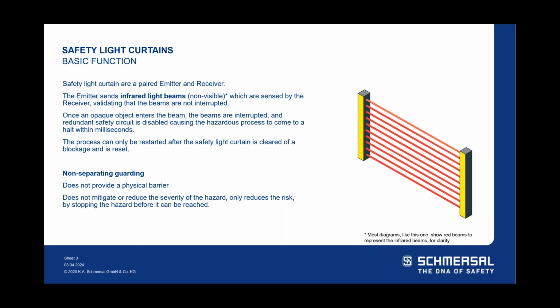All right, basic functions of a light curtain. Safety light curtains are a paired emitter and receiver. You'll see in our part numbers, there's an ER for emitter receiver. They come as a team. The emitter sends an infrared beam. We put in here not visible, although in our photo here, obviously you can see the red beams. And in the fine print, we tell you when you implement these light curtains, you won't see those red beams. But they're sensed by the receiver, validating that the beams have not been interrupted.